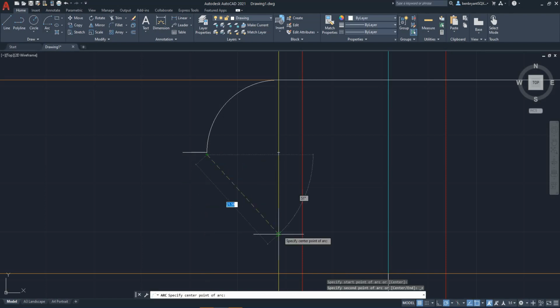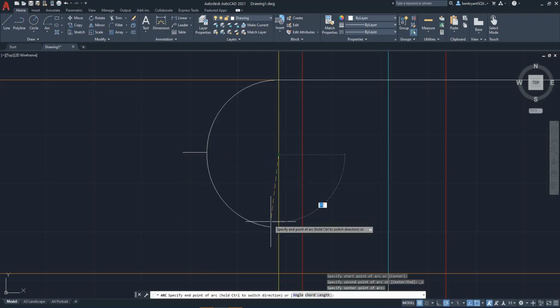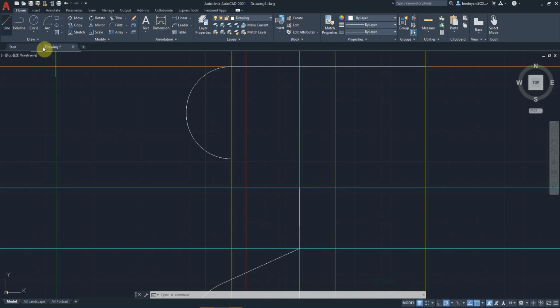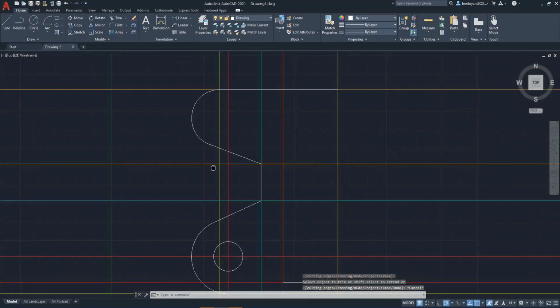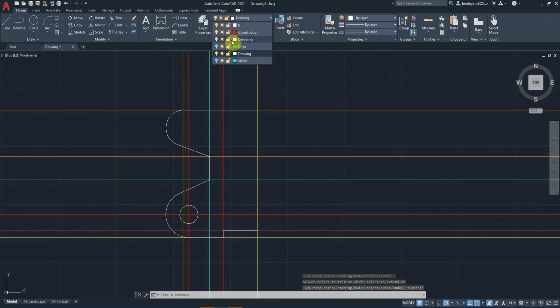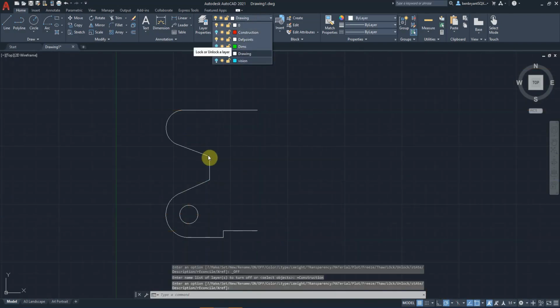However, you need to get the arc to sort of flick back this way and then come in and join at the bottom. So now the last thing to do is run my tangent line from here, which then brings it into that location. And I'm just going to trim out the remaining circle. So now when I turn my construction lines off, I have the profile shape, which I can then mirror.